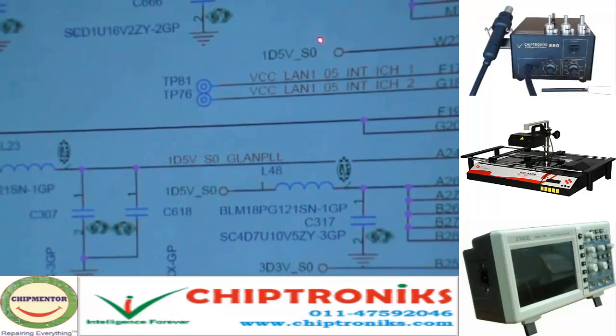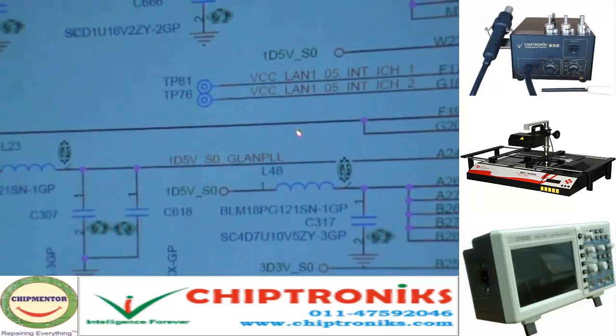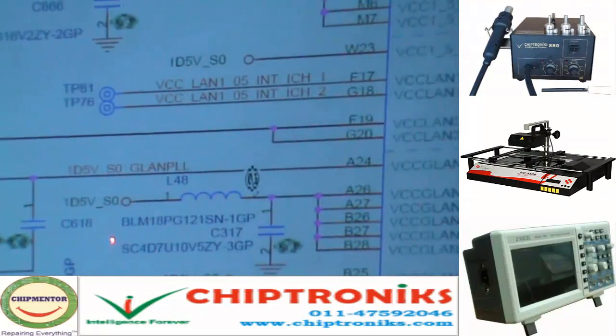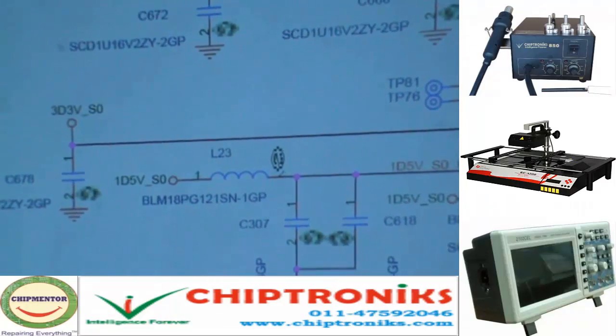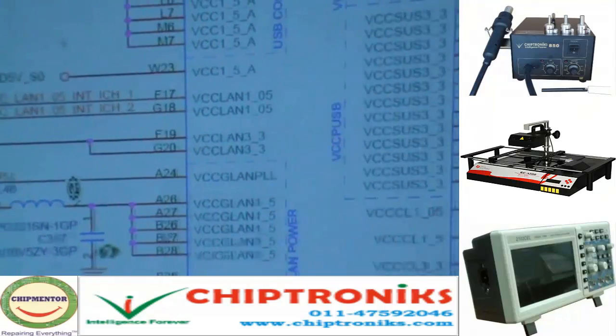Similarly for the LAN, there is a voltage of 1.5 volt. So if your LAN is not working, we have to check whether the LAN controller portion in the ICH is getting voltages or not. Then again 3.3 S0. So these are all the important voltages required for the working of the ICH.